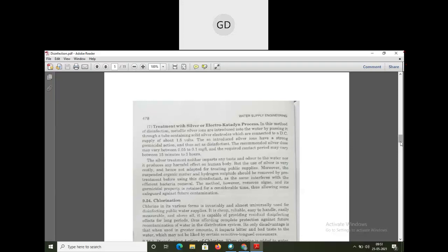So it has some chemical reactions also. Here you see this chlorine, when it is added to water, it is forming HOCl plus HCl, that is your hypochlorous acid. Then this hypochlorous acid that is formed is very unstable in nature, so it will easily break down to hydrogen ions and hypochlorite ions, OCl minus.